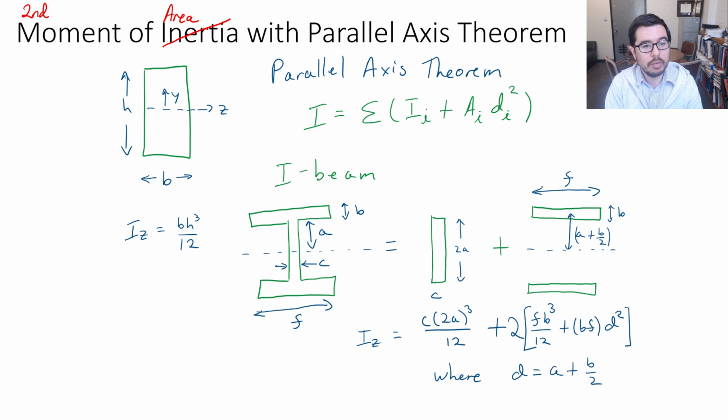We now have another tool in our box for looking at the decomposition or composition of complex shapes using simpler ones, like a rectangle that we've discussed previously, rather than going straight to the integral of y squared dA for the second moment of area.